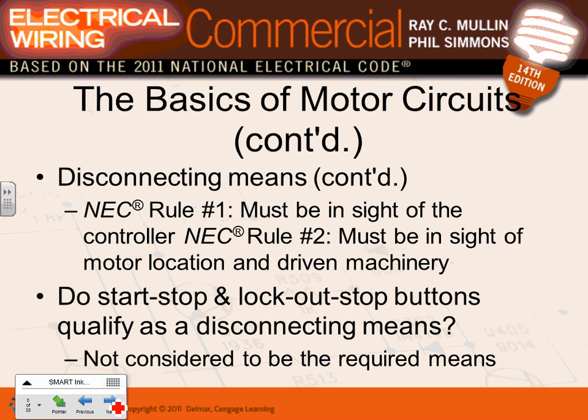This is the most important thing, guys, for us as designers and for safety. Disconnect rule number one, there are a couple of rules: it must be inside of the equipment, and must be inside of the motor location and driven machine. We'll look at it in a second. Start-stop does not qualify as a disconnect, no consideration by the code. So the start-stop buttons that you see here, they're not disconnects.